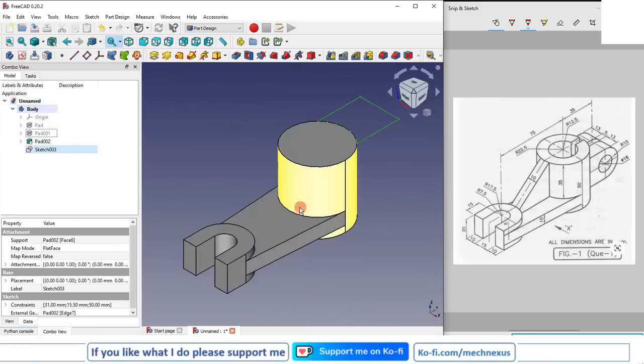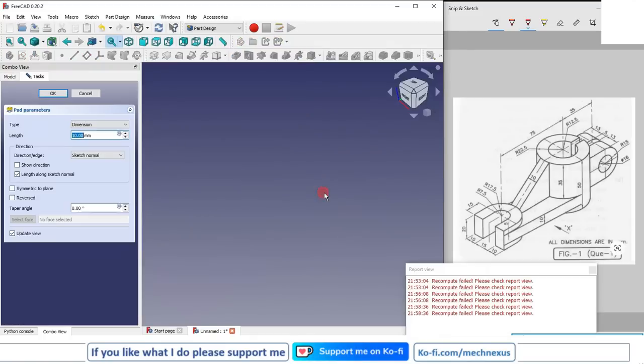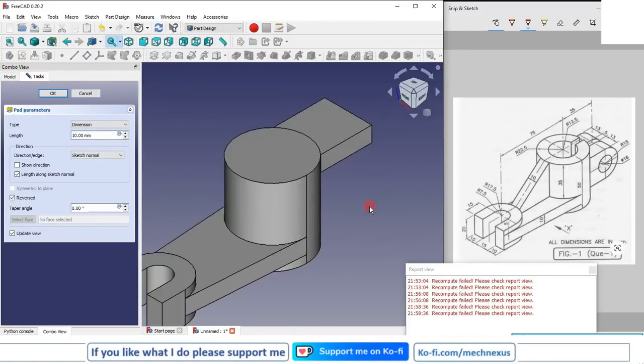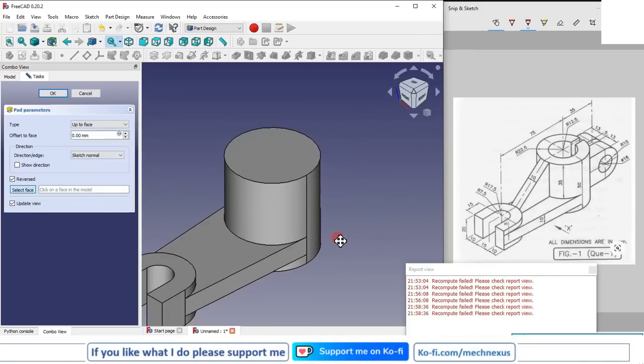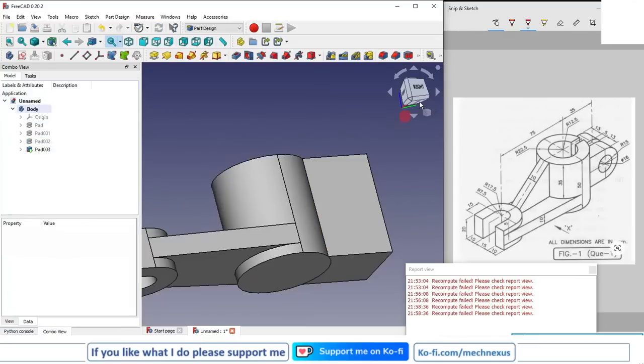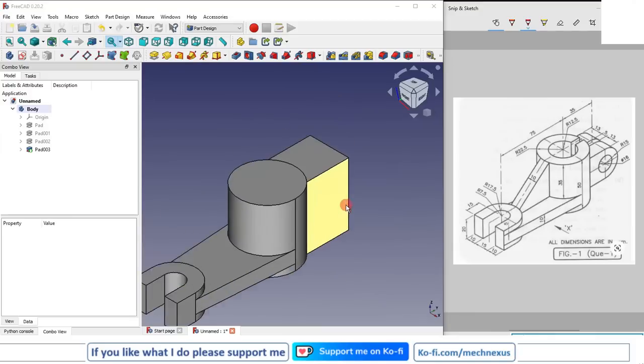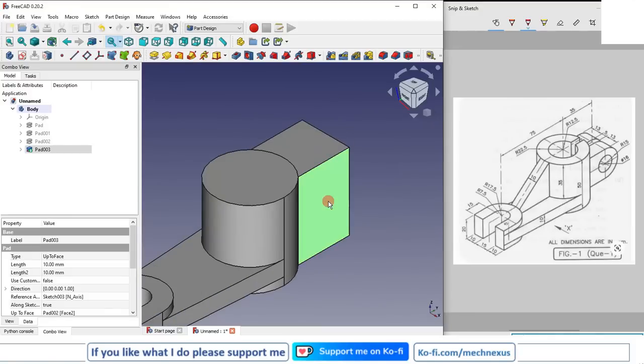Now I will close it and I will make the pad, and I will select up to face, rotate my model. So first I will create the solid and then I will remove the material. Now I will select the face, now from top and bottom I will simply remove the material, then I will apply the fillet.